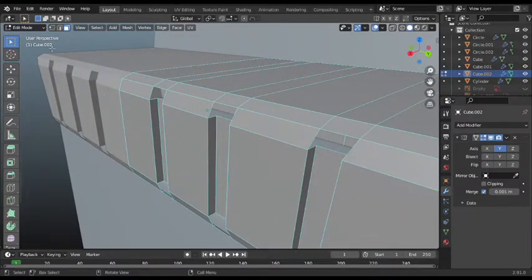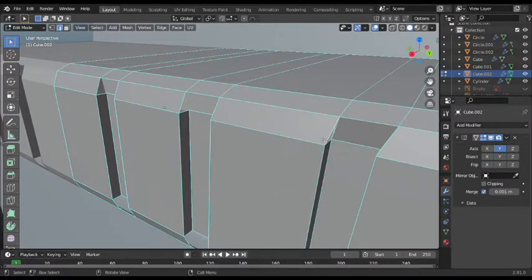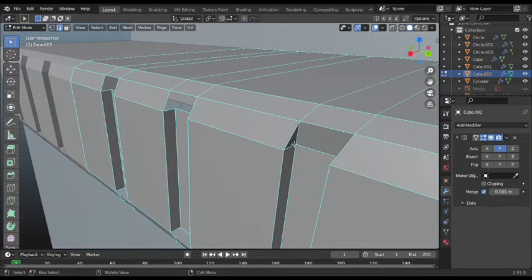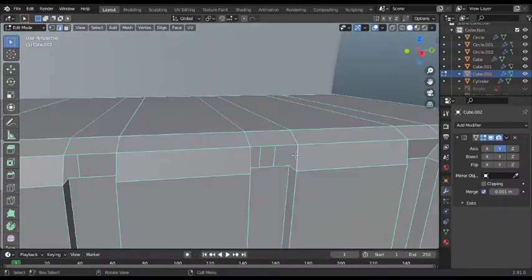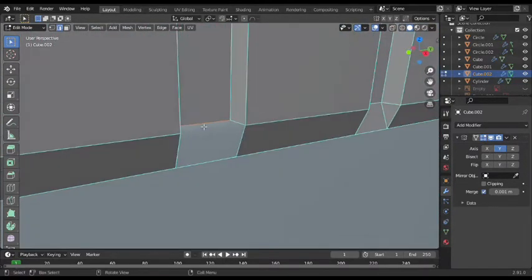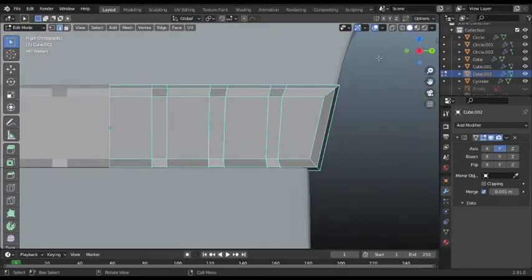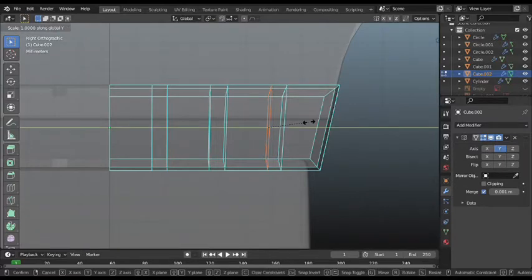Nothing to worry about. I'll fill them up by selecting these two edges and pressing F at the same time. Selecting one of these triangles and pressing F at the same time again. Doing this, F. I'm gonna switch to X-ray mode and make sure that they are straight. So for that I'm gonna press scale about y-axis and press 0.